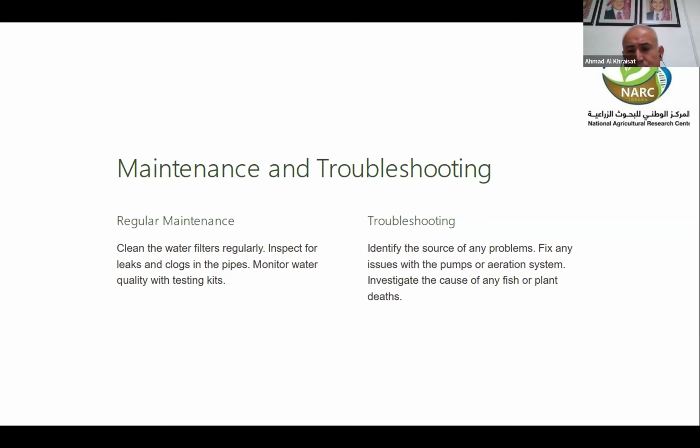I suggest putting other pumps or blowers beside them, because when one is not working, the others can work directly after that. This system cannot afford to take time, because it is very risky and we have an intensive fish population in this system. So we need to act directly for the water.